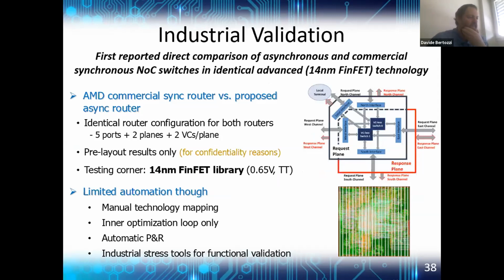This asynchronous switch has been compared against a commercial counterpart, an AMD commercial synchronous router in 14 nanometer FinFET technology. This is the first direct comparison of asynchronous and commercial synchronous NoC switches. So the asynchronous NoC was instantiated to reflect the architecture of the commercial synchronous counterpart from AMD, with 2 planes and 2 virtual channels per plane, similarly to what the Loihi chip is doing. Although we achieved the post-place-and-route results, let me now just report post-synthesis results for confidentiality reasons.